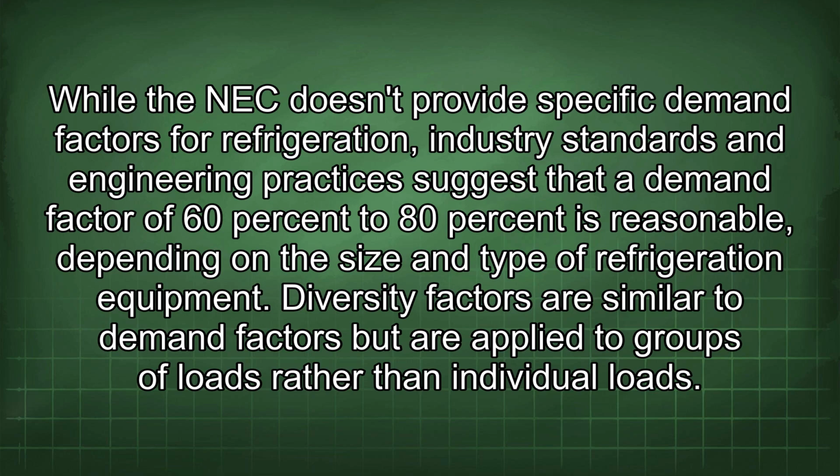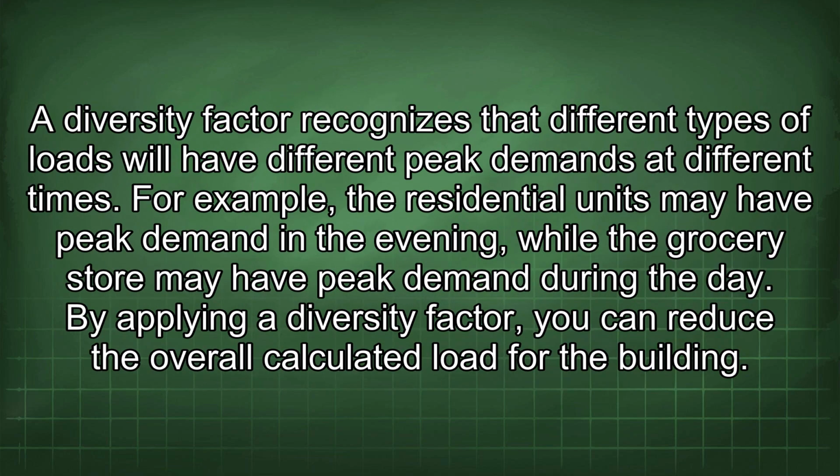Diversity factors are similar to demand factors but are applied to groups of loads rather than individual loads. A diversity factor recognizes that different types of loads will have different peak demands at different times. For example, the residential units may have peak demand in the evening, while the grocery store may have peak demand during the day. By applying a diversity factor, you can reduce the overall calculated load for the building.